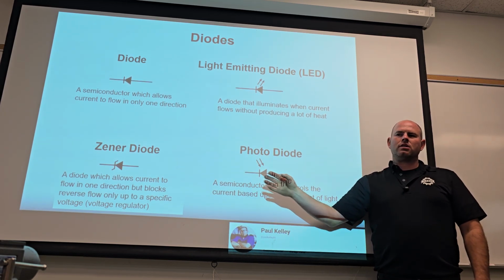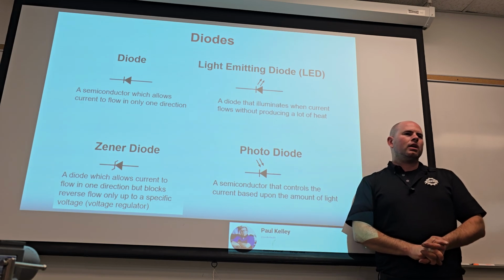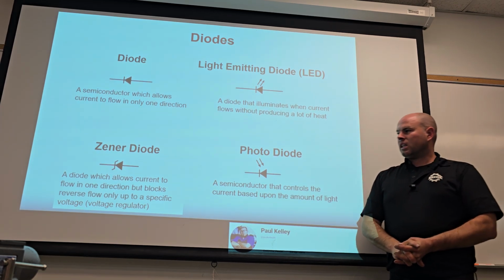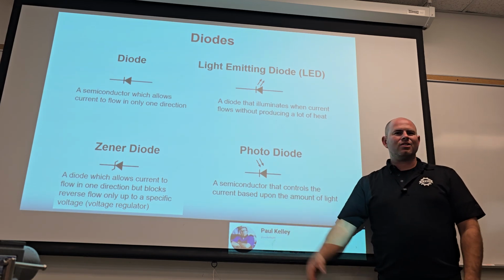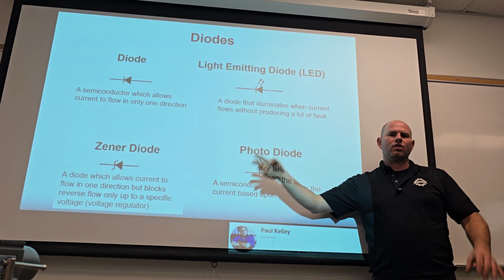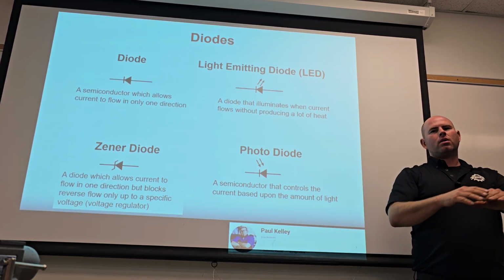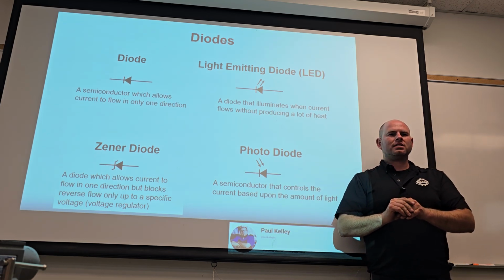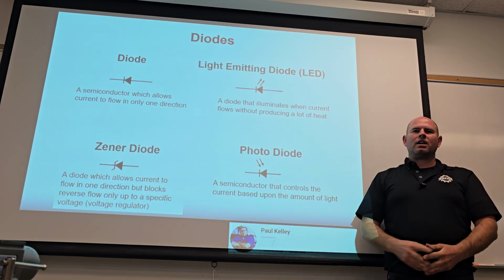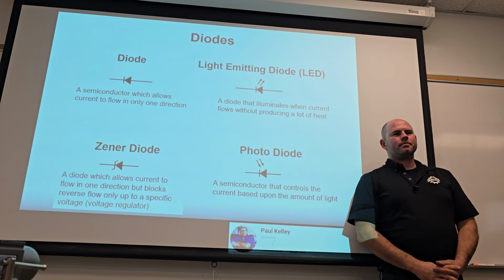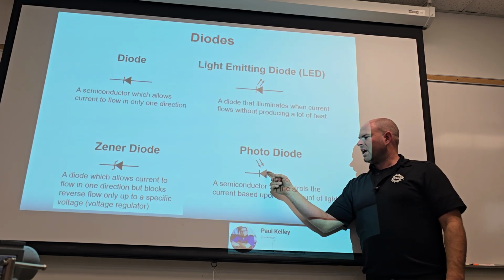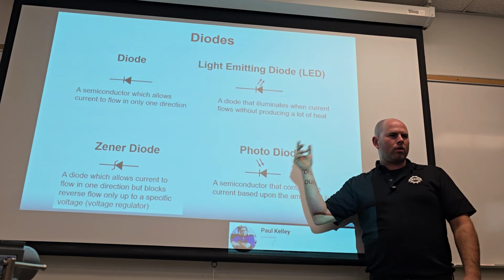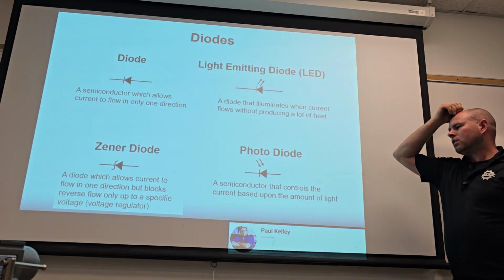So this is another sensor that's an input to your HVAC system. If you're diagnosing a headlight problem, you may diagnose this. But if you're diagnosing air conditioning, you may diagnose this. And that's why I like to cover the actual electronics of the components. Because in the later classes, we'll just discuss it as the ambient light sensor. We won't go into detail about it being a photodiode, with less light, less current, with more light, more current. Cool.